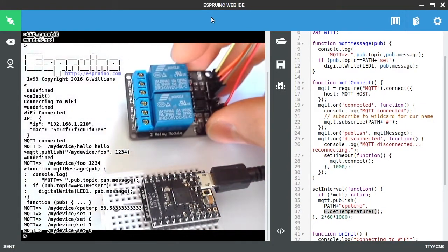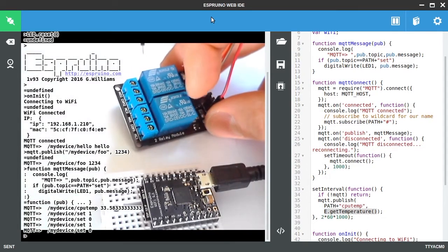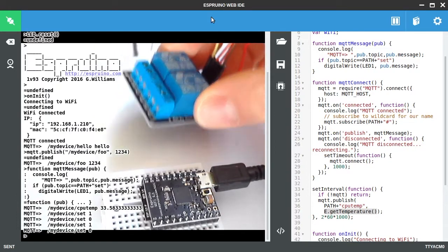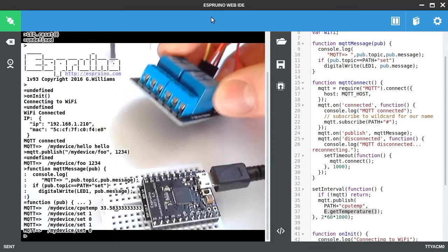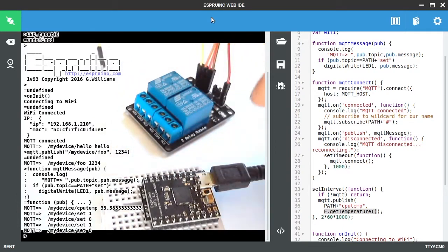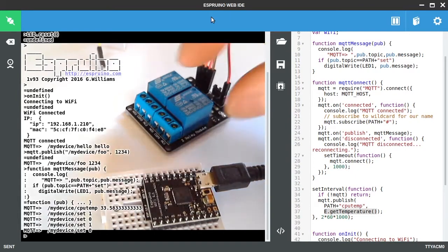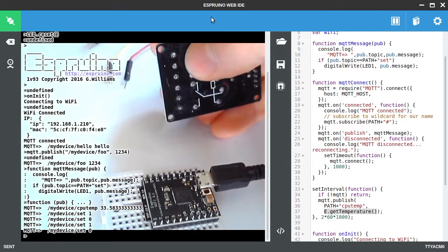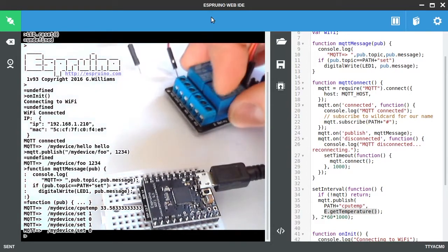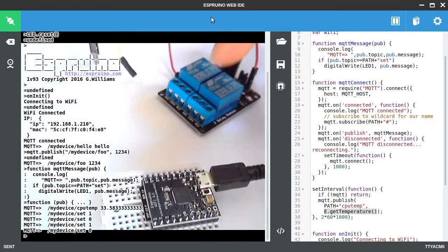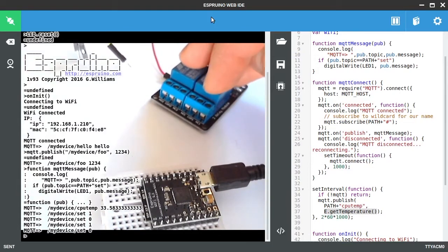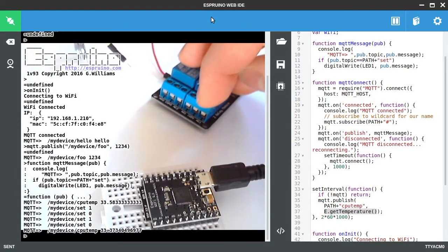This is a little relay module, so it's rated for 250 volts on this side, so you could quite happily turn on lights and whatever just by connecting them to the connections here. You can see that on the back it's marked where this is normally closed, so effectively between COM1 and NC will normally be connected, but when the relay is active it will instead connect common and normally open one.